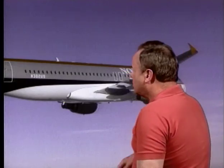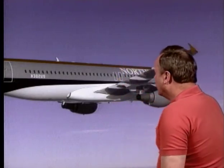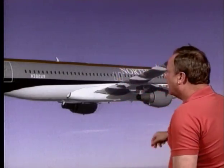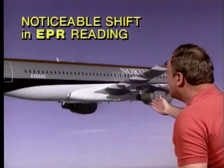And what gauge do you use to measure thrust? EPR. So the whole point is, if you're flying along at a constant power setting in an airplane and you turn on engine anti-ice, you will see a noticeable shift in the EPR reading, and it'll be a shift down because you're operating with less dense air.